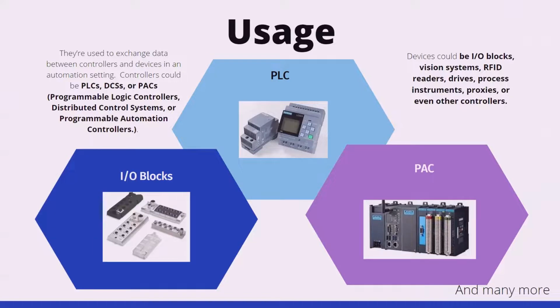Profibus, along with Profinet, could be considered an undisputed world leader in the area of industrial communication protocols. Since Profinet is an open standard, hundreds of manufacturers have developed Profinet products such as PLCs, PACs, robots, proxies, diagnostic tools, and so on. Profinet supports 256 devices using communication paths such as IRT, RT, TCP, IP, and so on. And Profibus supports 127 devices, and with over 50 million devices installed by the end of 2017, it is a well-established technology used in many different control systems.